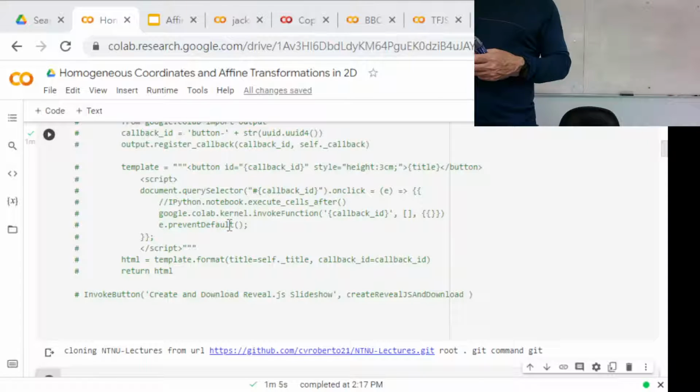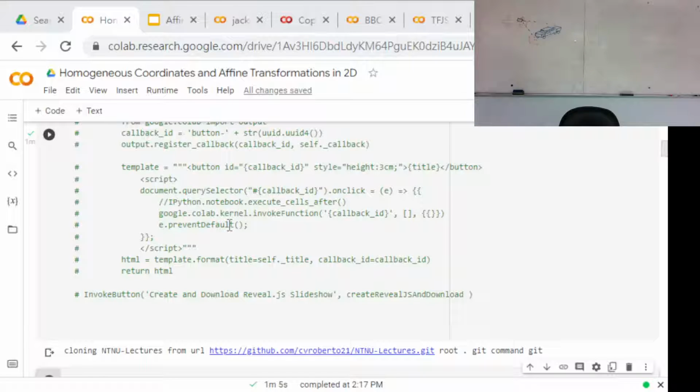we have to track the ball. If I want to track the ball with my robot, then if I only have a single camera, then detecting the width of the ball or the height of the ball is one possibility, but that's quite noisy, very error prone, because the resolution of the cameras on the robots are not very good. So we would get a lot of noise in the detection of the ball using the size, even though we use that for our soccer playing robot as well.